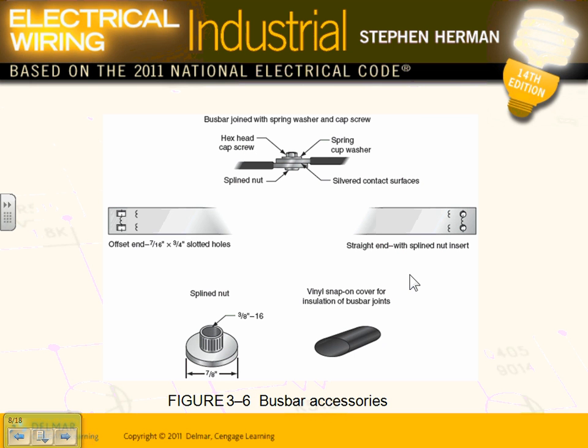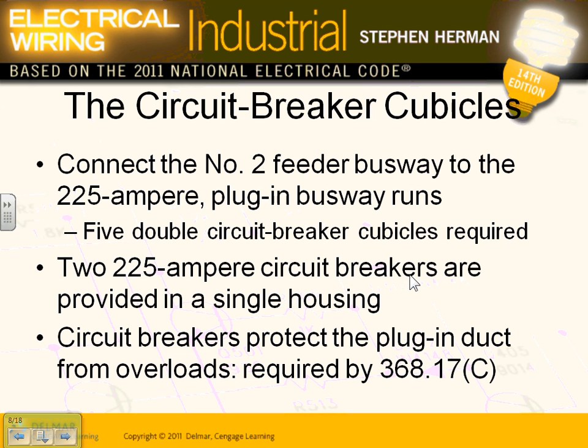This just goes through the hardware, guys. Busways require a lot of maintenance, not bad, but you have to do maintenance on them. You have to de-energize them, adjust them, and torque them, because there is a lot of copper bus inside them. They have circuit breaker cubicles, they call it.